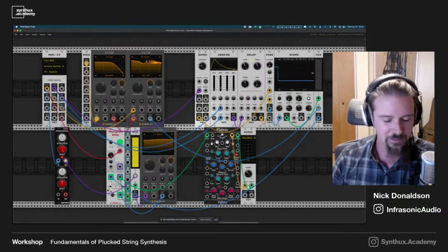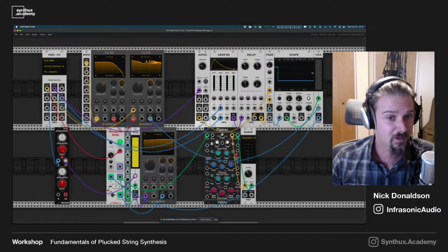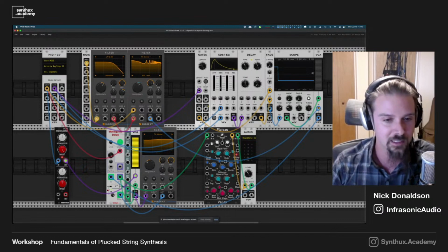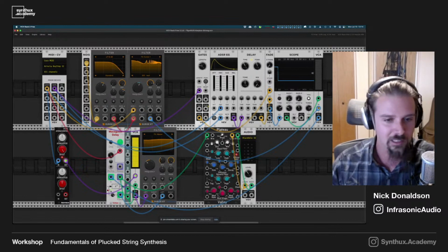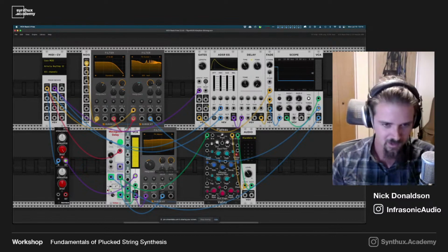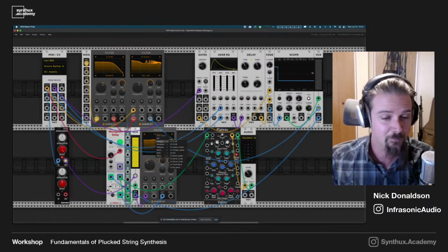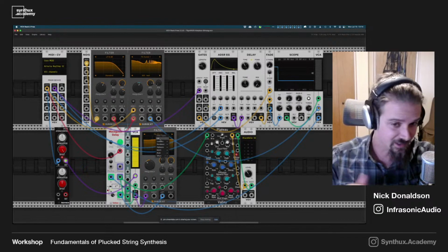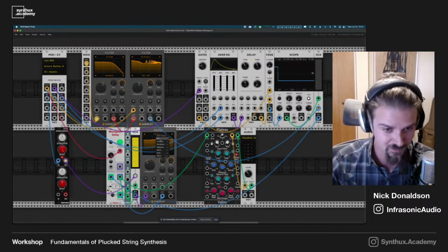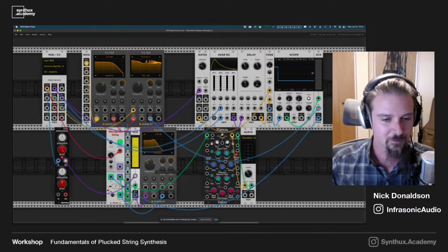So like a ring modulator or something almost. That is actually what the structure control on Rings, for example, affects. The way Emily did it is a much more extreme all-pass example. It can get really inharmonic, just sound totally outlandish, not like a string anymore, but like some crazy inharmonic out of tune physical system. That's all just done by putting basically an all-pass filter in the feedback loop so that each harmonic has a slightly different delay based on the phase response of the all-pass filter, and we get crazy sounds. So that's one thing the Rings code can do.